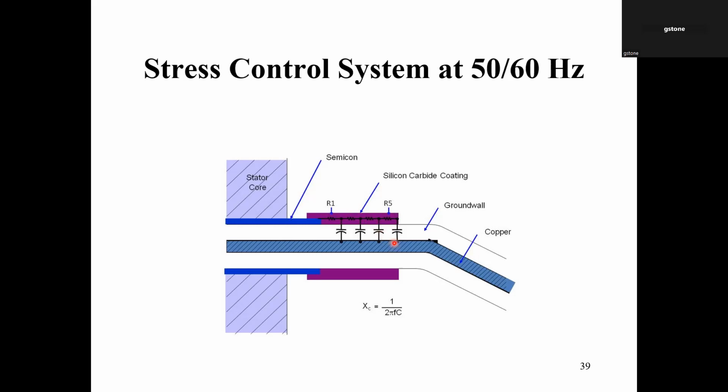And the idea here is by the capacitive currents flowing up through here, the currents will flow through that resistance, and these resistances will self-adjust to make sure we have a linear voltage drop across each of these resistors. Okay, so that's how it's supposed to work.